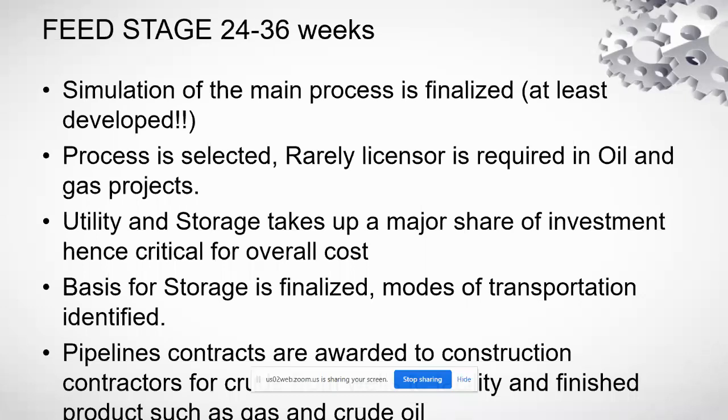so rarely is a licensor involved. Next, the biggest aspect is utility and storage, which takes up a major share of investment, hence it is critical from the overall cost point of view. When we talk about utilities, it includes steam, if at all it is feasible at some sites. There are some sites, particularly in deserts, where there is a very high shortage of water, so most of the time steam is avoided. So the heating utility is hot oil. Other utilities are instrument air, plant air, then nitrogen.